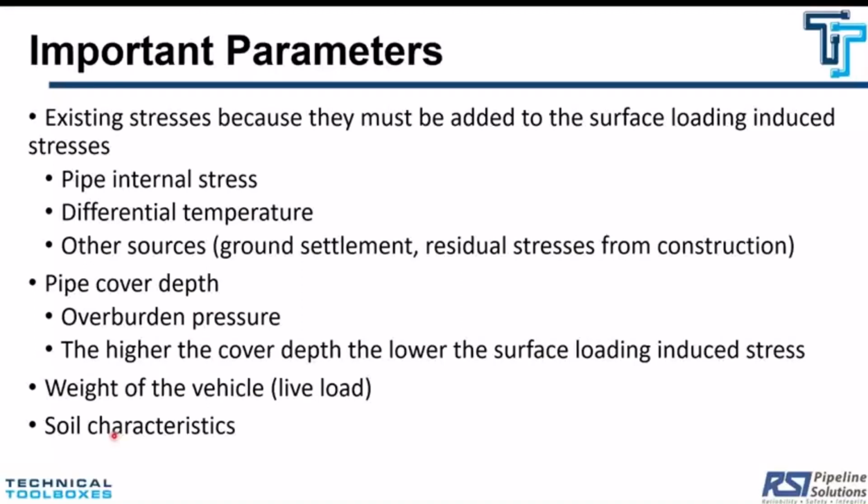So if you know the soil classification, there are some tables that give you modulus of soil reaction and unit weight and other things that you need to know. If you don't have soil classification, then you can always go with a conservative assumption. But regardless of what method you use, it's always best to get soil parameters from laboratory testing of soil samples.